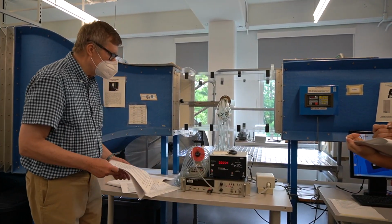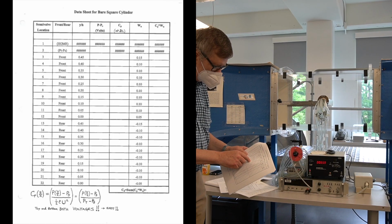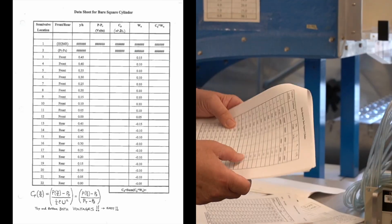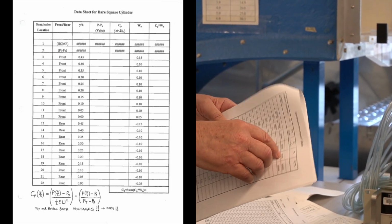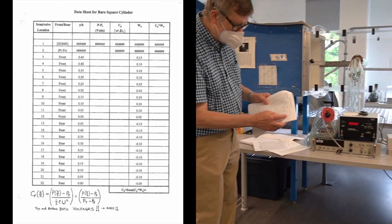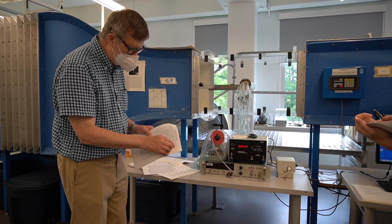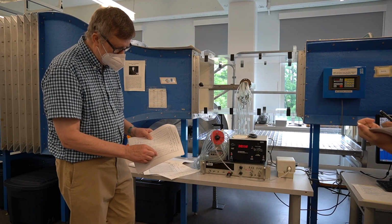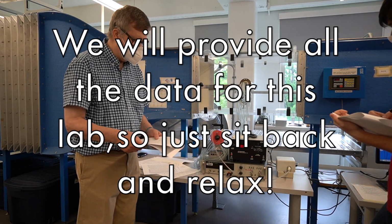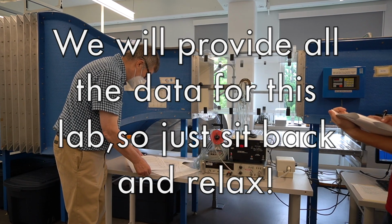So we're going to be measuring pressures at this point. We enter P minus PS in the fourth column and CP in the fifth column, then multiply that by the weighting functions, which is multiplying the pressure times the area. That gives you little elements of force. You add all those CP times weighting functions in the right-hand column, and when you add up all these data points, you should get an accurate determination of the drag coefficient of a bare cylinder. So let's see if we can do that.